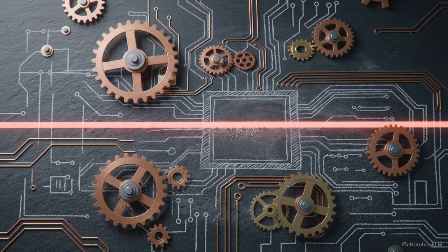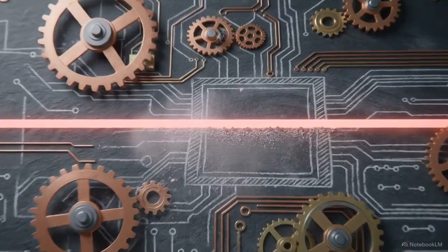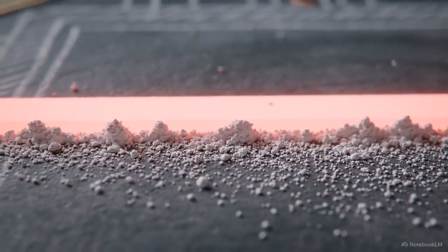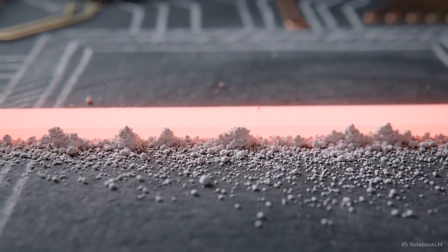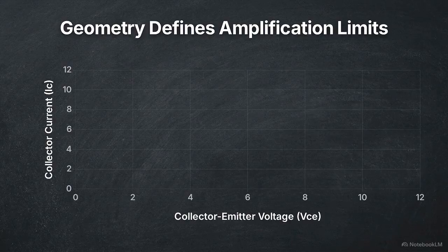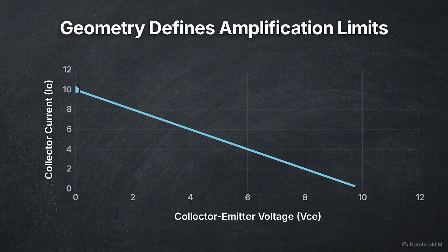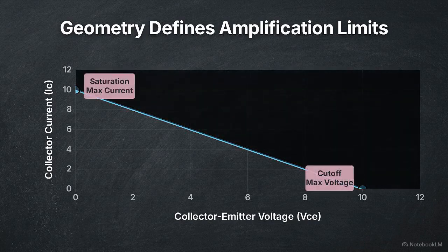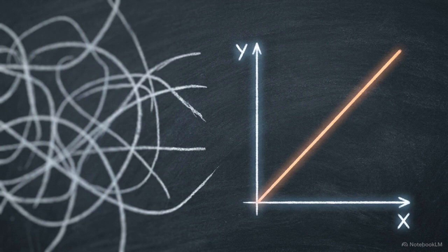Classification is determined entirely by a hidden two-dimensional geometric boundary condition operating inside the transistor itself. We call this boundary condition the DC load line. By deriving this load line from scratch, the physical limits of amplification emerge as a direct result of the circuit's geometry. Understanding amplifier class requires mapping the mathematical boundaries of the transistor's possible energy states rather than analyzing the physical